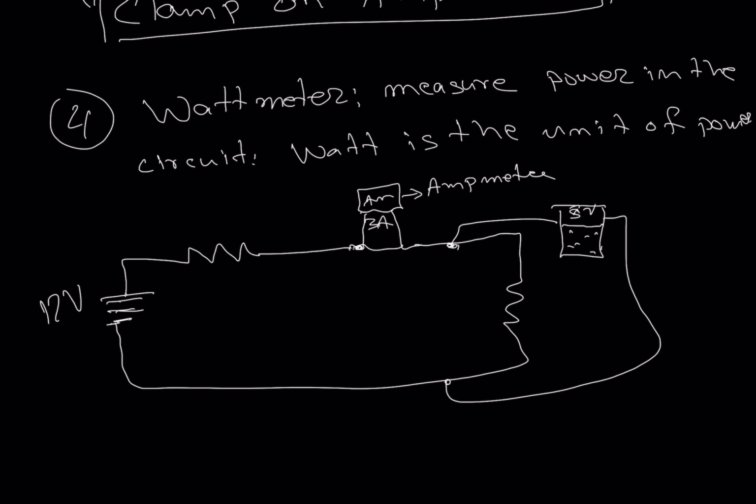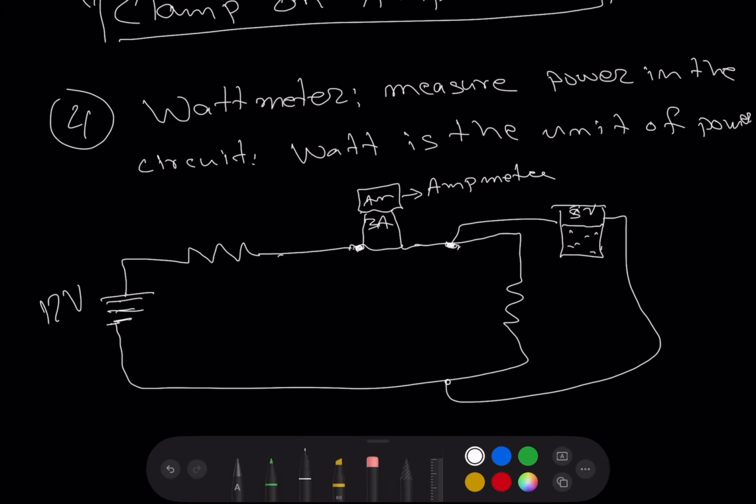That's how we have to put it, because it's power. To measure power, you have to have two measurements here, amperage and voltage. To measure amperage, you have to be connected in series with the circuit, and to measure voltage, you connect it to the load side of it. So you can do it right here, measuring the load voltage of this circuit.